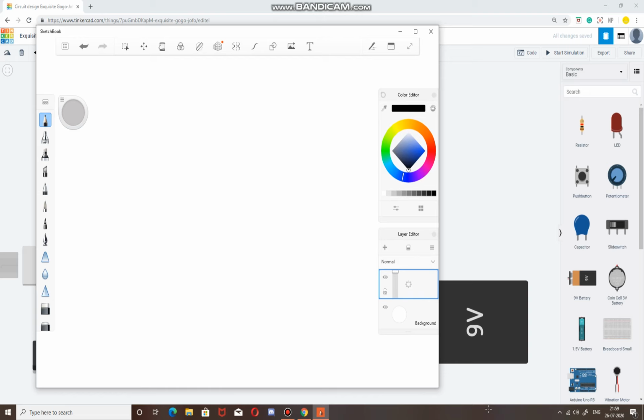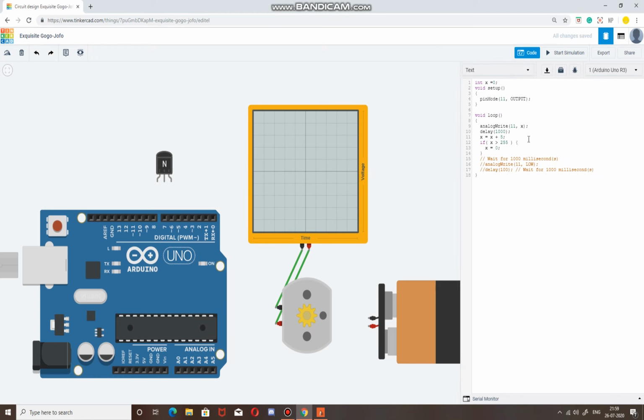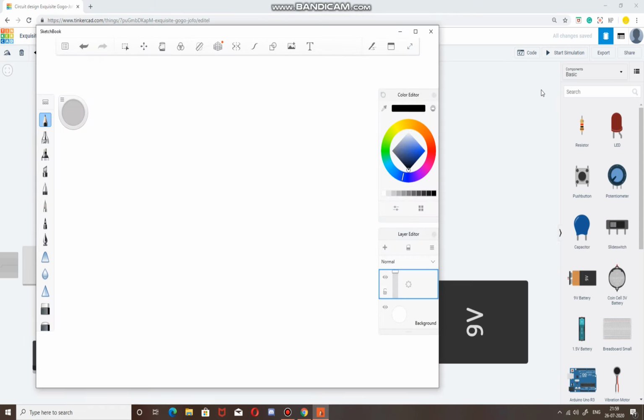Now yesterday I did explain pulse width modulation, but I explained it something like this. What I understood originally was that the signal, because we are using the code, which I'll show you, shows as analog, right? Now I thought that the signal was actually an analog signal. Now that's a wrong concept that I actually taught you guys, and I want to correct that part. Although we are using a function called analog, it does not actually produce an analog signal. It produces a square wave or digital signal only.